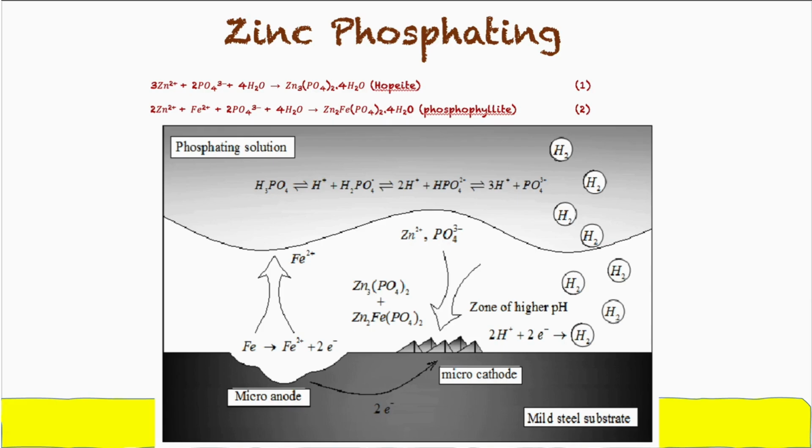That means chromic acid is not used, and instead we use 0.5 percent methyl trimethoxysilane, which is sufficient to give a pH of 4 for better performance than a chromic acid rinse.